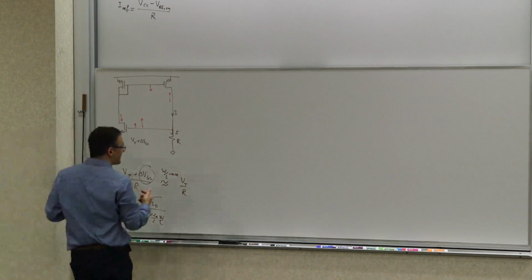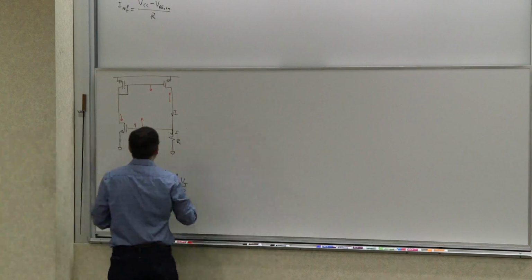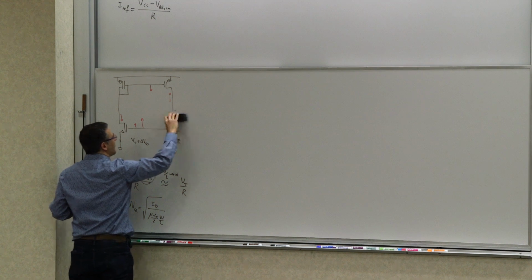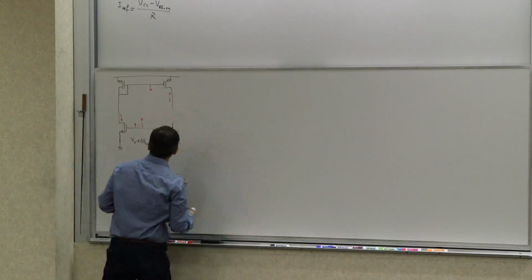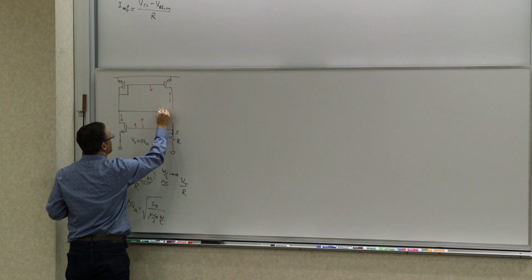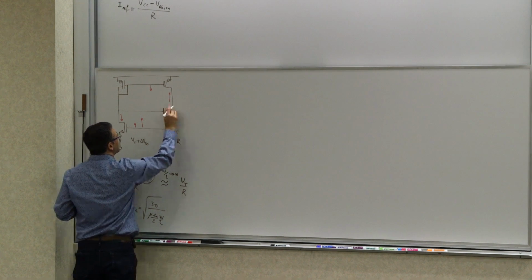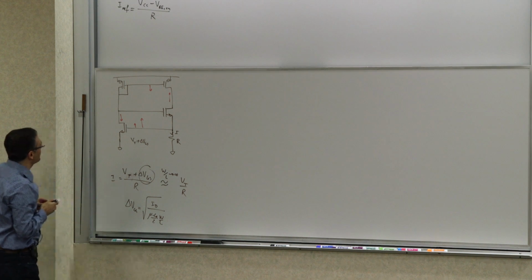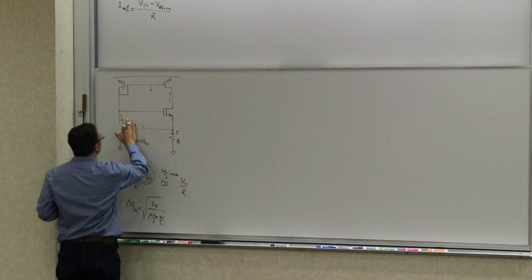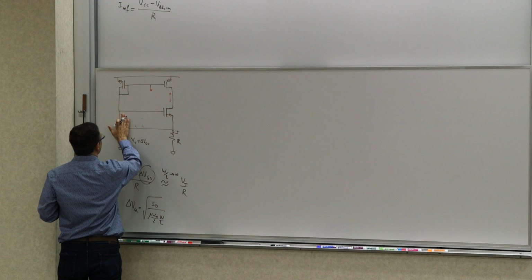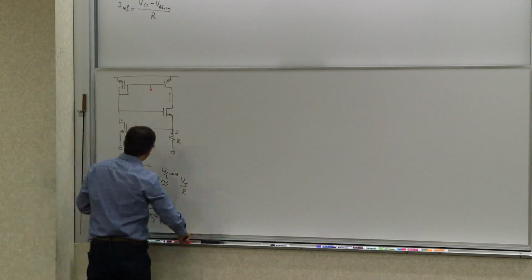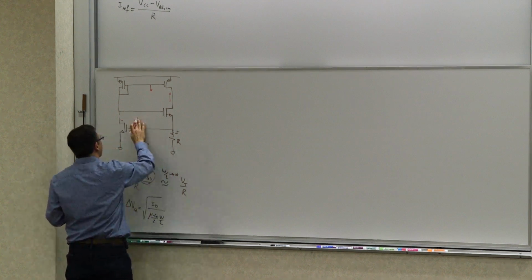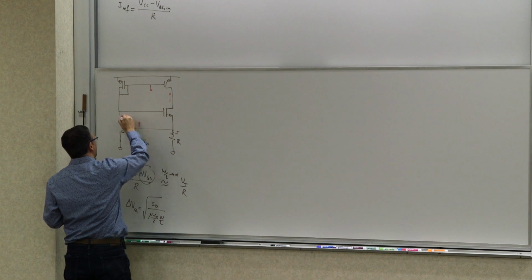So we have to kind of break this feedback loop. One of the ways you could do this is to put another transistor here to create that isolation. What you do by doing that is that you can see that now the loop within this pathway has a negative feedback. And again, we haven't gotten into feedback in detail. We'll get into it later.